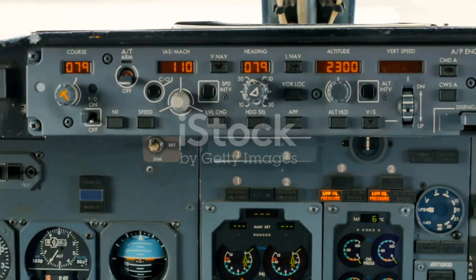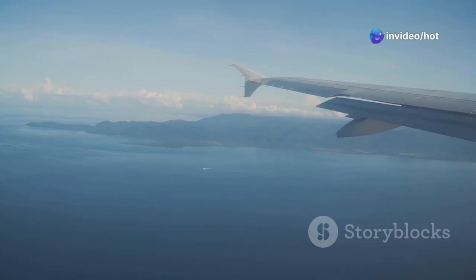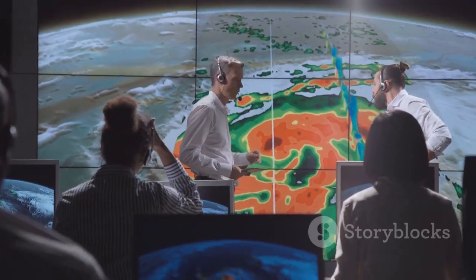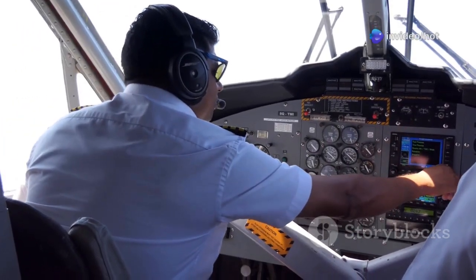What exactly is a flight level? It sounds like altitude, and it is related, but there's a crucial difference. Altitude is height above mean sea level. This is measured using the local atmospheric pressure. This local pressure changes with weather. It also changes from place to place, so true altitude readings can vary. This variation can be a problem for aircraft separation.